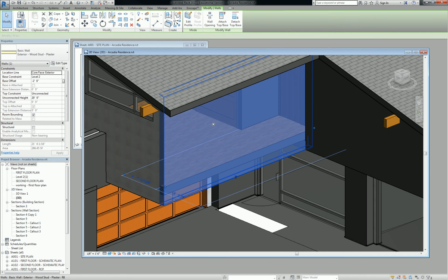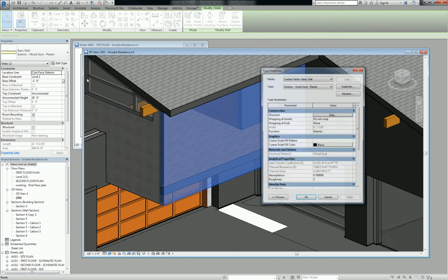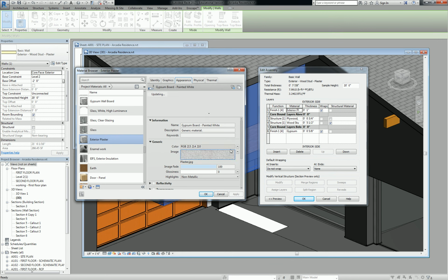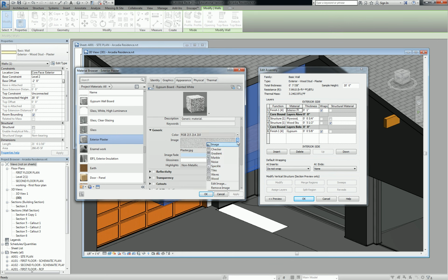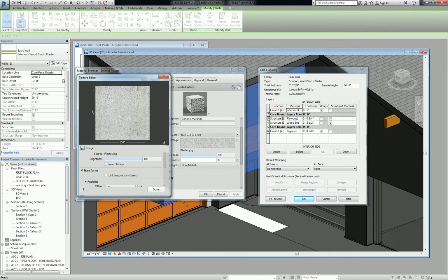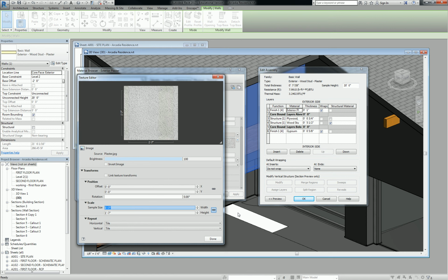If you need to change the scale of the texture map, go into Edit Type, go to your Material, Appearance, and Edit Image. Okay, Edit Image is where you define what the scale of the element is. And you do have the ability of changing the dimensions rather easily. I can either disassociate the two sides and make them different sizes. So I can make plank sort of conditions out of square maps, and I can take rectangular maps to make them square.